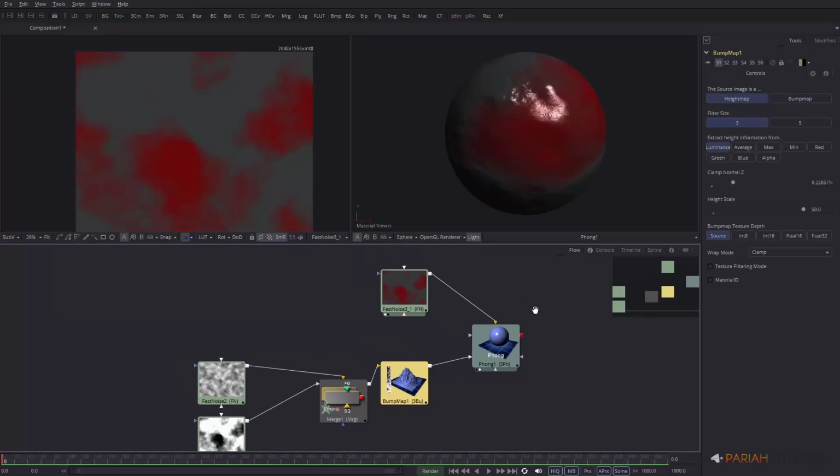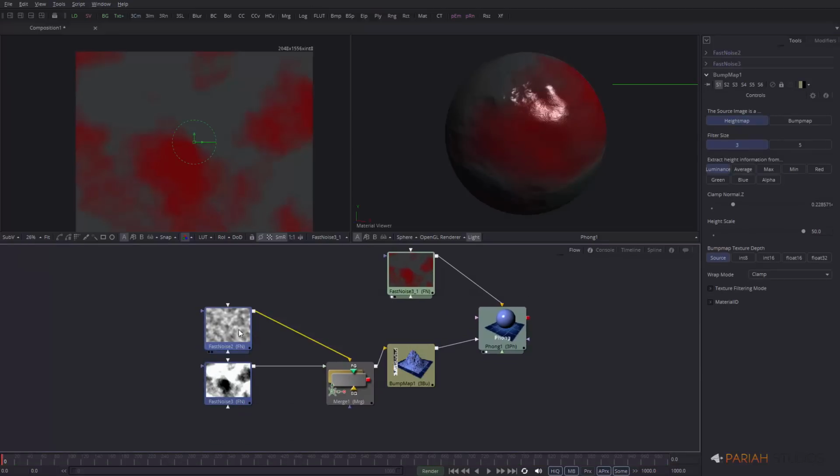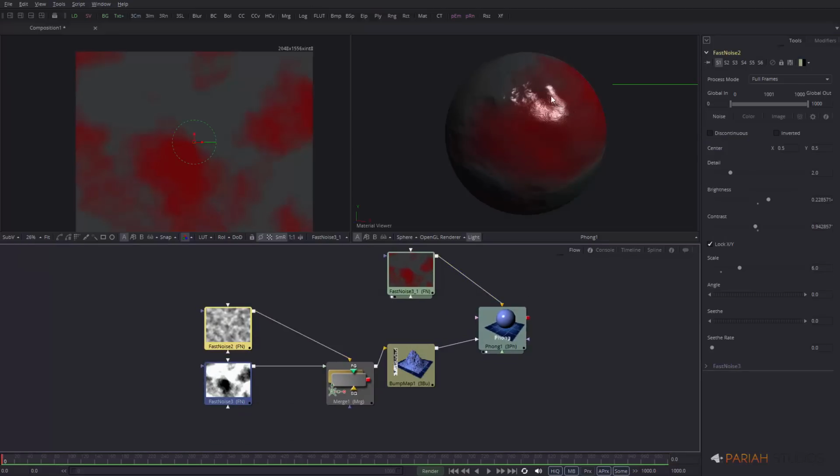And so that's a quick introduction to just making a very simple 3D material. And because there's some geometry built into Fusion, you'll need a way of getting texture and materials onto it. And this is how you would do that. Although you can use these materials on imported assets from your main 3D program like Cinema 4D and Maya, whatever you happen to be using.